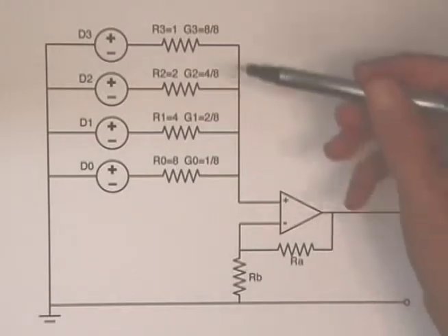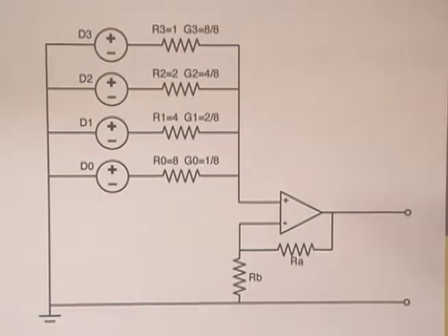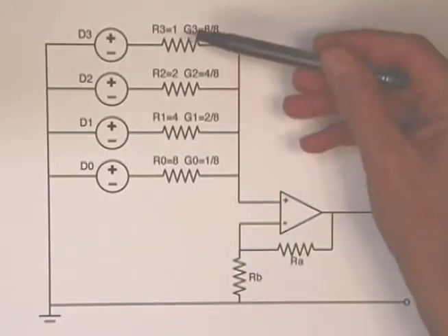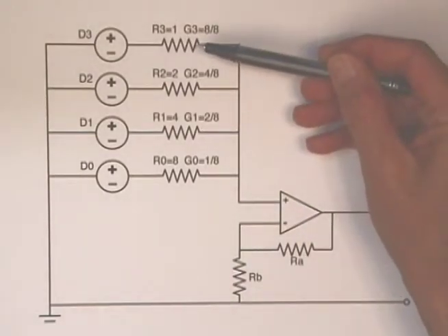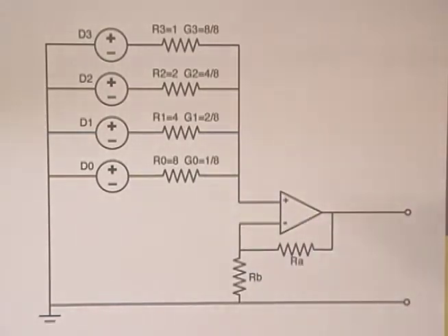The second comment has to do with the precision of the resistor ladder. The metal film resistors I used have 1% precision, but if I had 8 bits of input instead of 4, that would mean that a 1% error in the most significant bit would have the same weight as the entire least significant bit. This is difficult to address with discrete components.